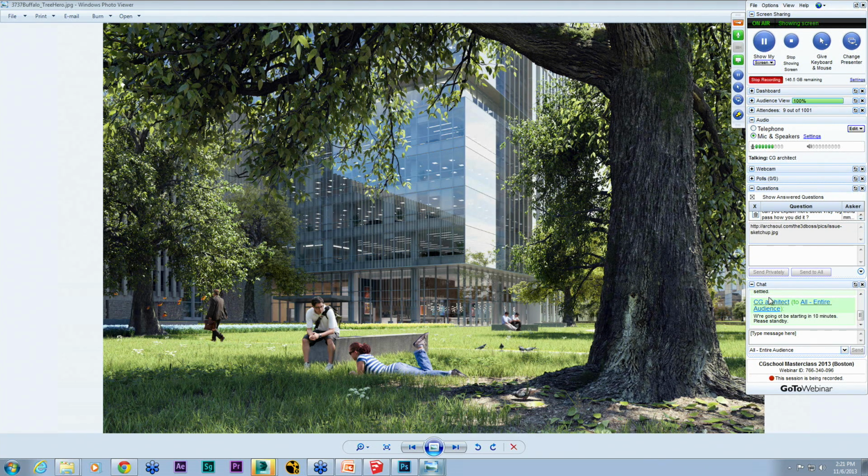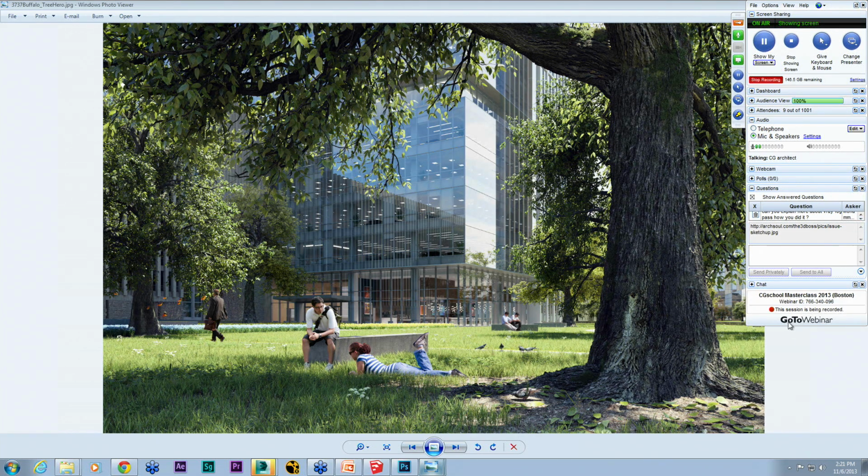If you find a good IES profile for the type of light you're using, it's really beneficial. It just adds an extra layer of realism to what that light would actually do in real life. You have good contact shadows on the surfaces that are surrounding that light. It is more reliable than putting just a strict V-Ray plane into geometry, we think.